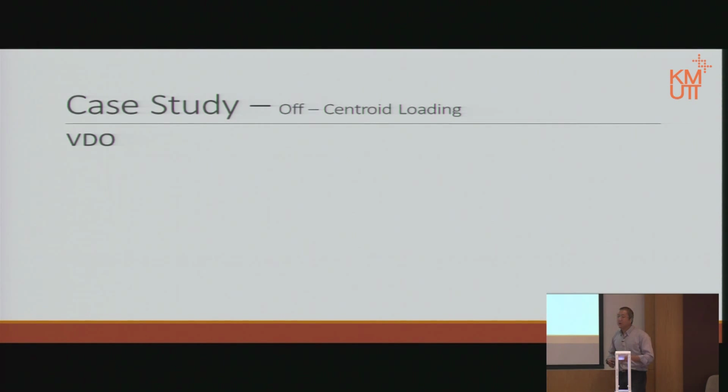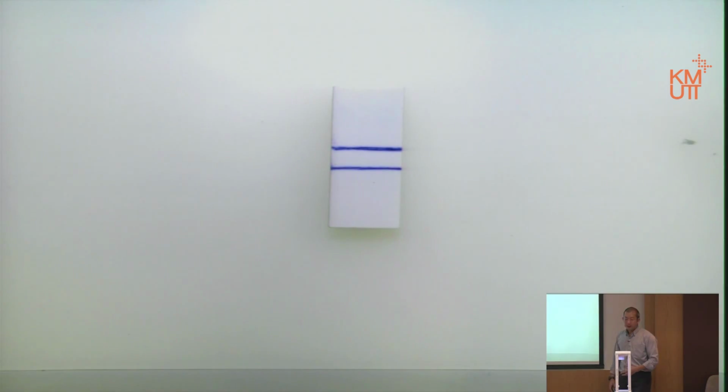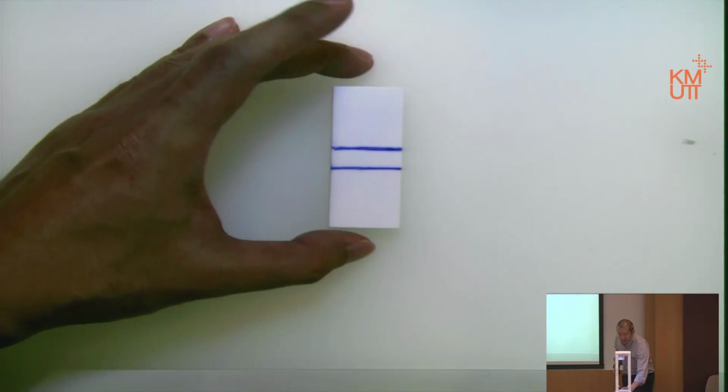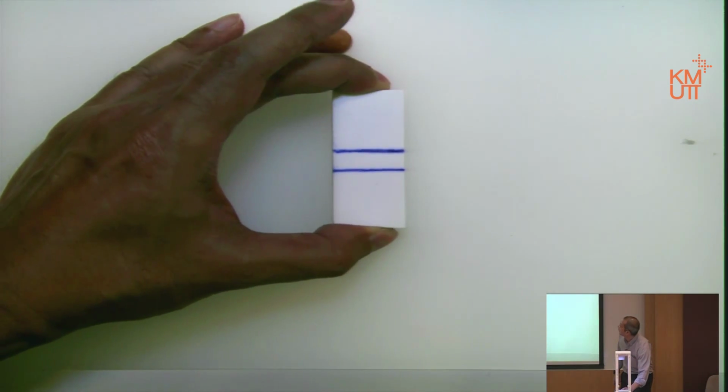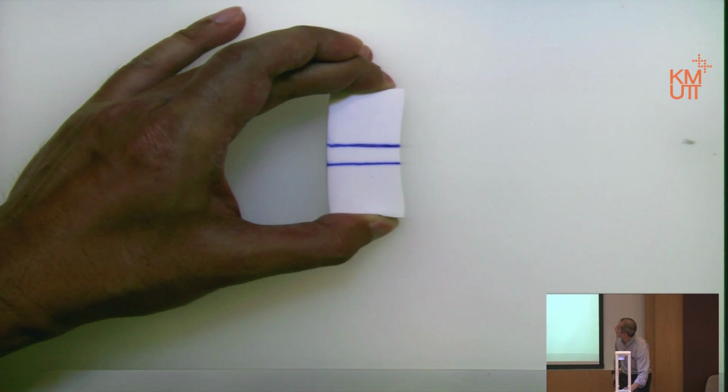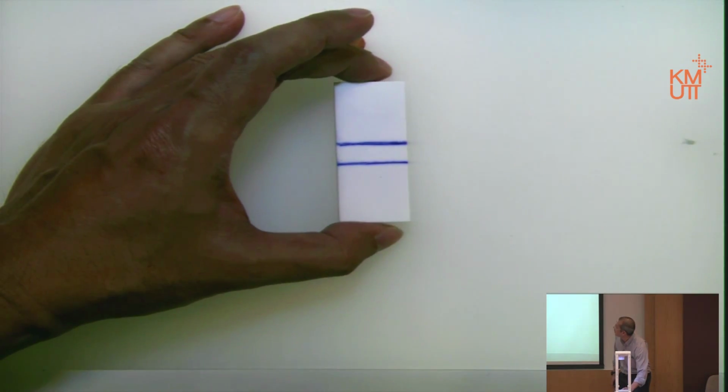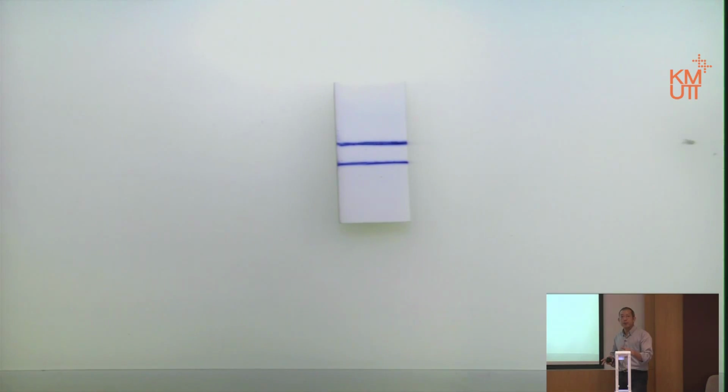We're talking about what we call off-centroid loading. This is the same rubber I have been using to demonstrate the effect of axial force and the effect of bending moment. If we think about this in terms of my demonstration of how axial stress works, notice that it goes down straight into each other, and when I release, it separates in a straight line. No bending, it just shortens and then becomes the same. Or if I pull it, of course it will be longer, and then I release it, it becomes the same length.